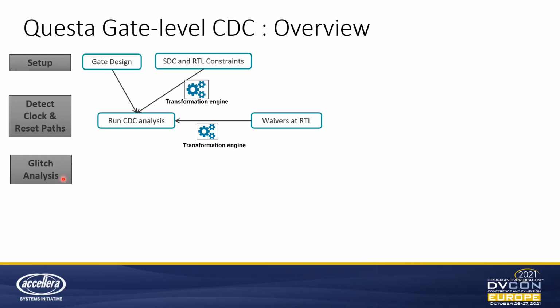Let's say we have multiple registers that are driven by the same combinational logic. Now we identify this unique combinational logic and then do one comprehensive expression-based analysis on this combinational logic tree to identify the potential glitch candidates that can cause glitch to propagate. Once we identify this potential glitch signal, we do formal analysis on this.